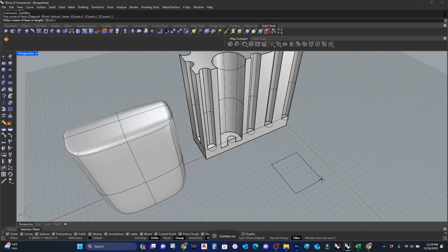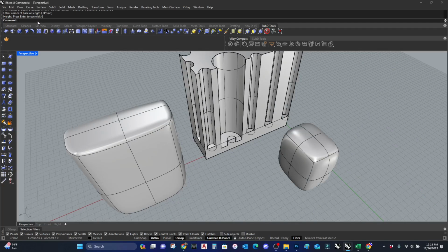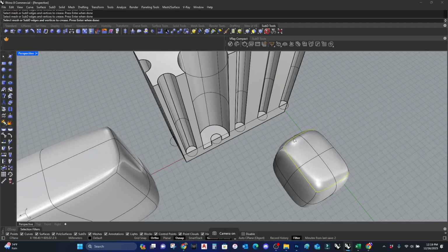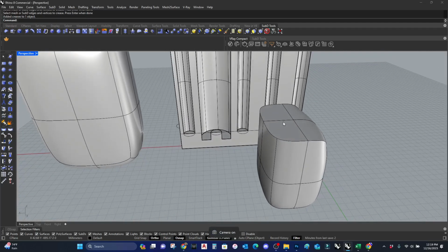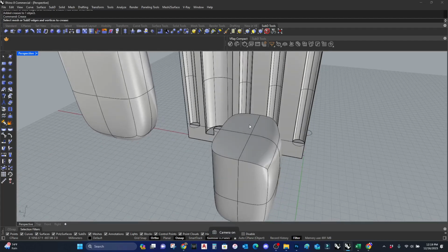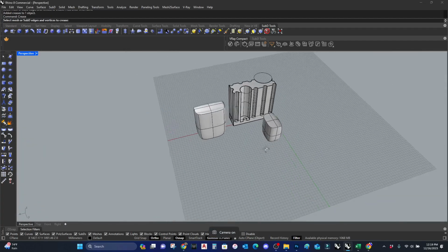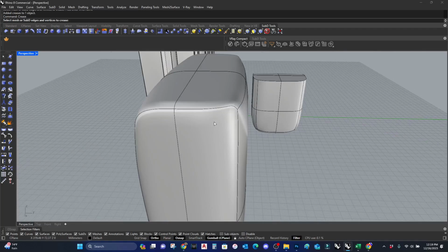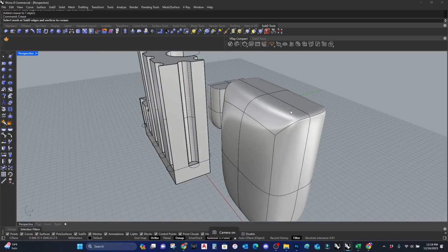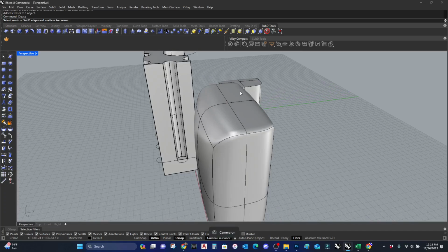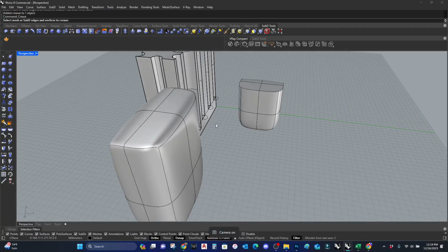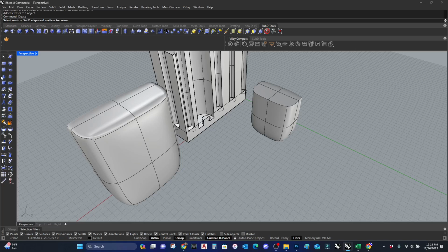Before this command came out, there was only a crease command, and you can see it right here. If I just type in crease, it's only defaulted to 90 degrees, and you can't select a particular angle. So this is also a really nice little key, and especially if you're working on some industrial design project, having these multiple creases with multiple radii is really nice.